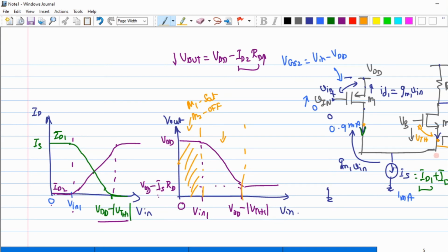I have a fixed potential Vb, and no current has to flow means the VGS of this device has to be equal to Vt. So, how will I read this voltage in terms of Vb? Vb minus Vth. Okay. So it purely depends on the value of Vb that I have chosen. Now, from the value of Vb, I have dropped down a value of Vth, and that is supposed to ensure that my transistor M1 is in which region? Saturation. It can be saturation, but it purely depends on the value of Vb.